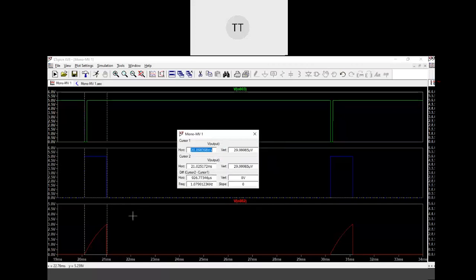One more important thing is that the capacitor can charge up to what voltage? Can you see it's going up to 3 volts? VTH, sorry, there is no question of VTL here. Up to 3 volt. VTL is related to your trigger voltage. So the trigger should be less than VTL, and when the capacitor voltage exceeds VTH, the output goes to 0. Correct?